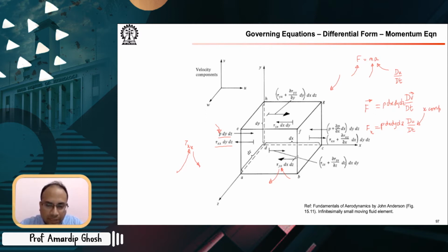We think of something like this, and essentially, when you rub your hands, one hand tugs the other one along its direction. So we are comfortable with that description or that effect of viscosity. But this tau xx, which is a compressive or expansive force normal to the surface due to viscosity, is a little less appreciated, or sometimes there is some confusion around it.